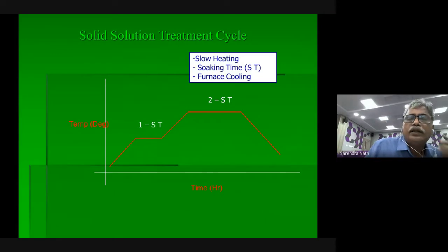And for solid solution treatment, what we are going to do is slow heating and soaking temperature. This is the first soaking time, to remove any kind of things that are there. Then this is the second soaking time. I didn't put any time; you can take any amount of time, it is left to you. So I have shown the general curve here.